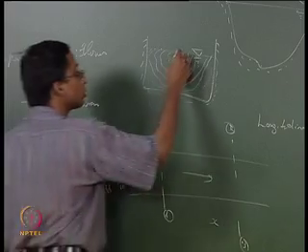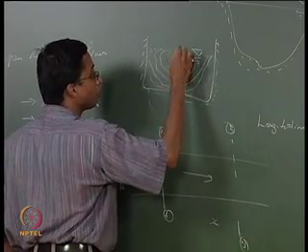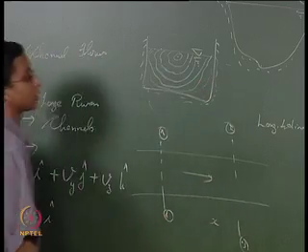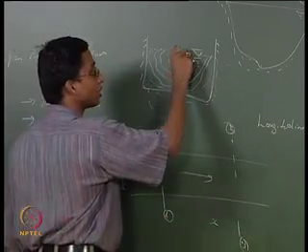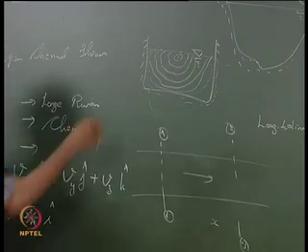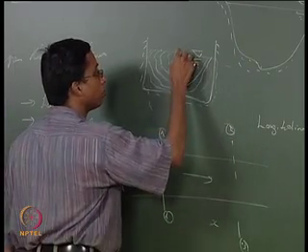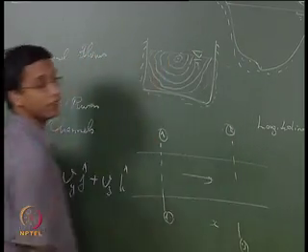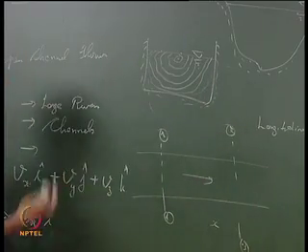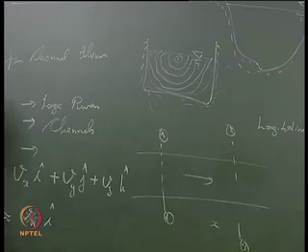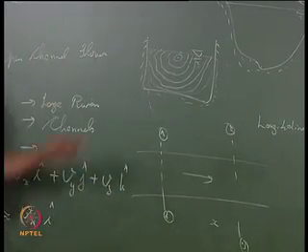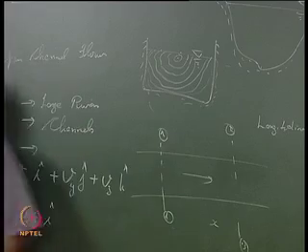Surprisingly, you may also see that the maximum velocity point, normally found from various experimental studies, is not at the surface, which is the farthest point from the boundary. They are all obtained just below the surface level. Those points have also been identified through several experimental studies. We have to just see how the velocity profiles look like.